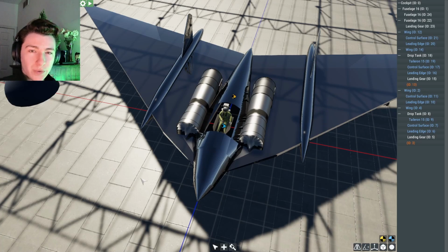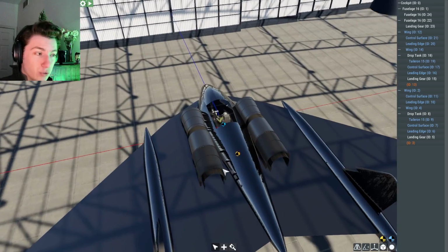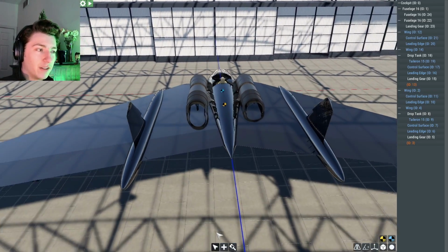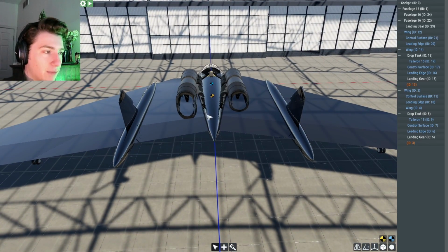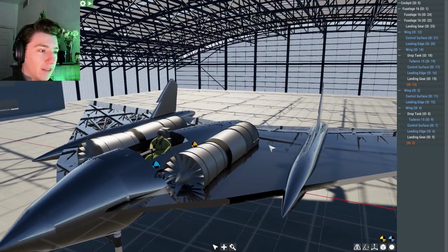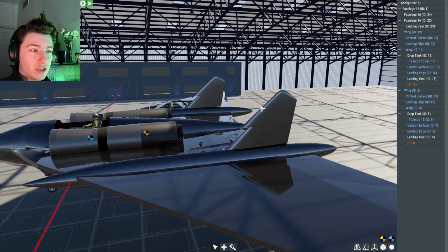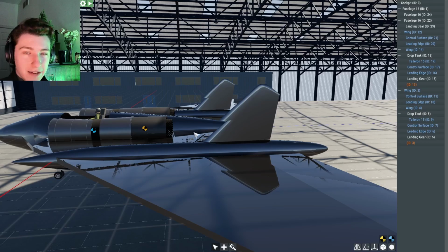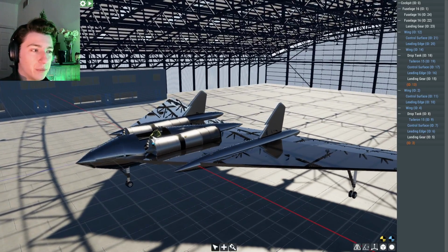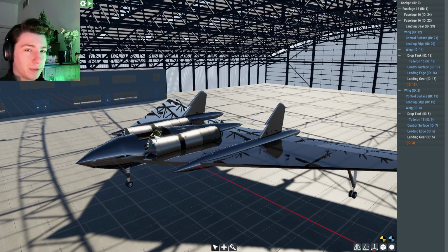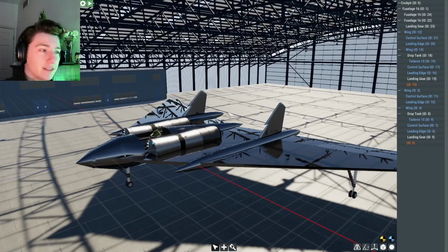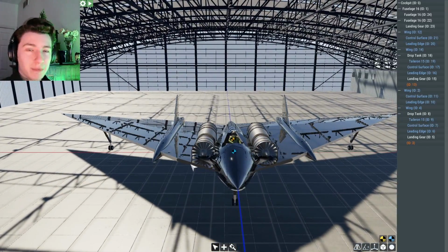Also, just a quick note that flying wings like this usually fall under the realm of unstable or not conventionally stable aircraft. And there are some advantages to that sort of setup where you have this conventionally unstable idea. One of which is you can actually get more agility out of a plane by doing this, because even though we only put a tiny bit of control input in to tell the plane to pitch down, the plane will automatically, without any further control input, pitch down harder and harder until we intervene in some way. So this is actually pretty common in modern fighter jets.